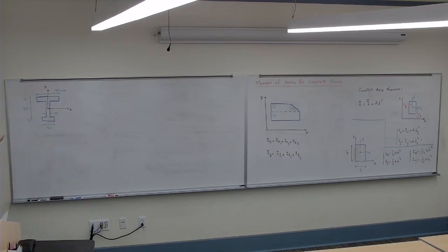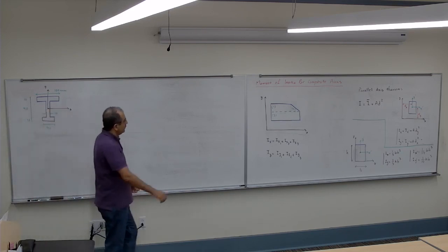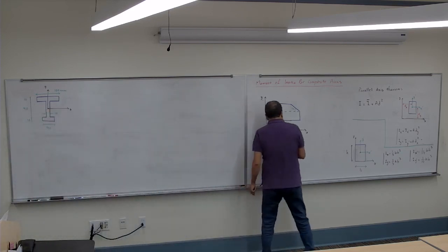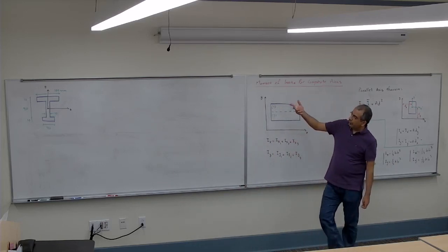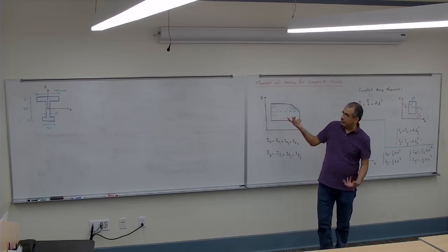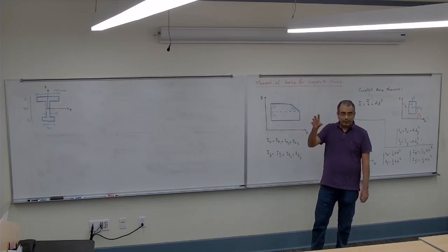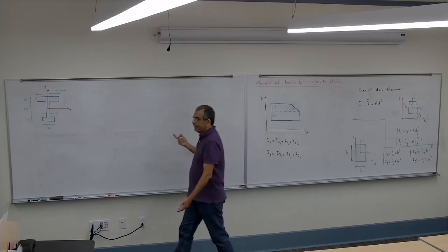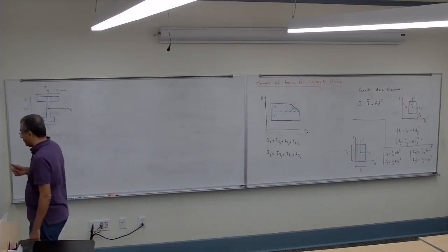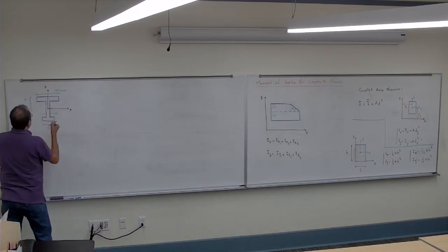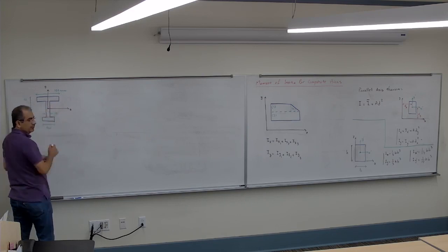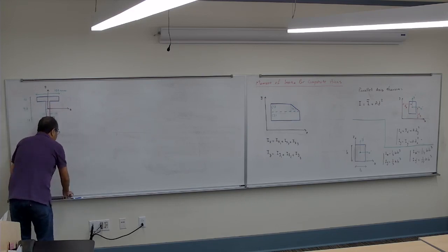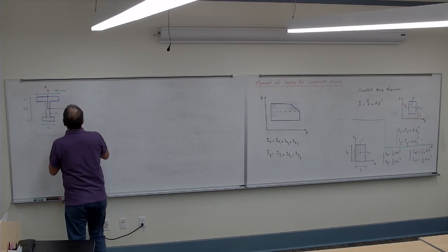So if I want to find the moment of inertia for that, I have to find the moment of inertia for each of those sections about the x. So I have to go ahead and start to break it down into shapes I know, and find the moment of inertia for each of them. So the easiest way that I can break it down is that I break it here and here. Top, middle, bottom. So I can say hey, I can break that into 3 shapes.